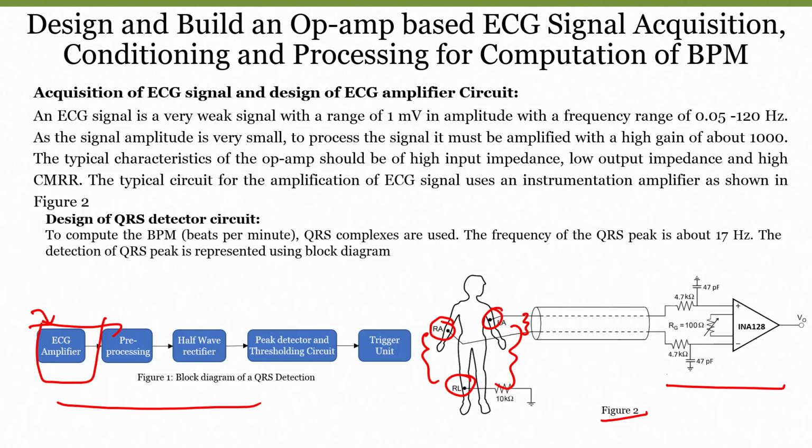The reason is that the input is directly connected to the non-inverting terminal of an op amp, because the instrumentational amplifier is made up of a 3 op amp based circuit. Whereas in a differential amplifier, the input has to be directly connected to a resistor, whose value decides the complete impedance of the system. As a result, the input impedance of the differential amplifier is really poor. So, we cannot go with a differential amplifier, and that is why we are going with an instrumentational amplifier.